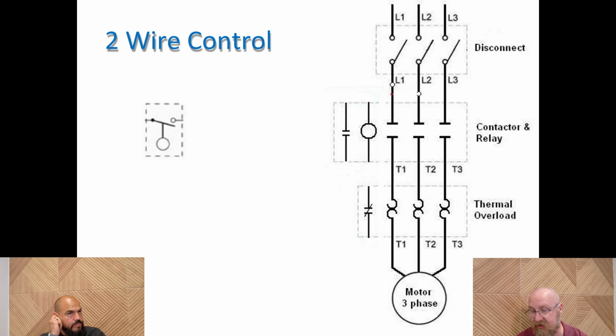So two-wire control is really good for those things that you want to be just controlled by a variable, and it's either on or it's off, and you're okay with that. But if you've got a push button, well, then it becomes a problem, right? So you'll see two-wire control a lot in automated things, like the float switch thing. This is sensing whether a level has dropped or a level has risen to the point where you need to pump the fluid out of that tank.